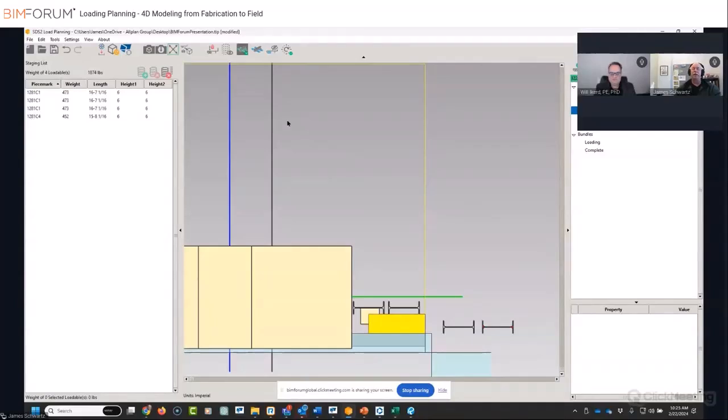And this is where this thing kind of sings. Urban environments where you basically have no place for shakeout. You have no place to lay this steel down. This is where this becomes very important because you want to make sure that the crane can pick off the trailer. I mean, again, we can spend hours going through things like what they are using on the site, RT, truck cranes, forklifts, how they're loading it, and that all kind of impacts it.